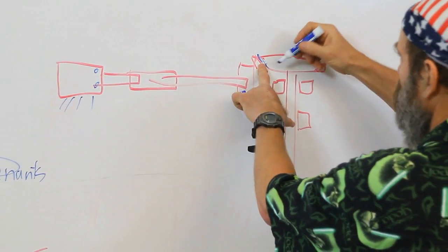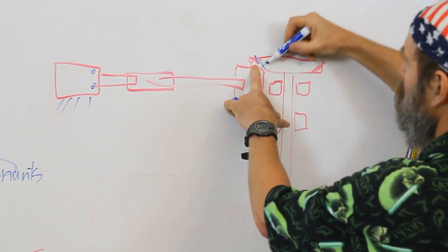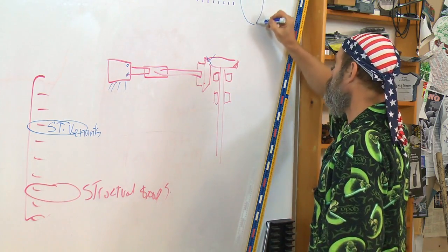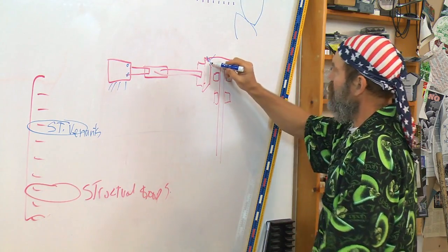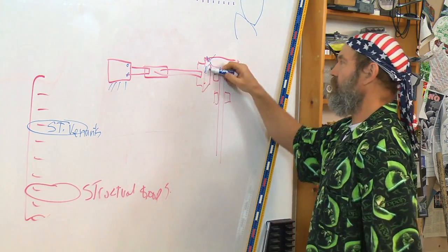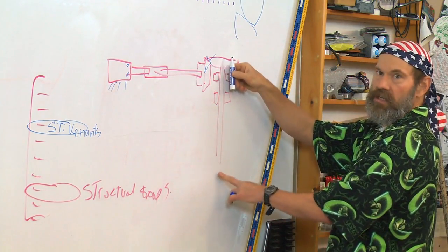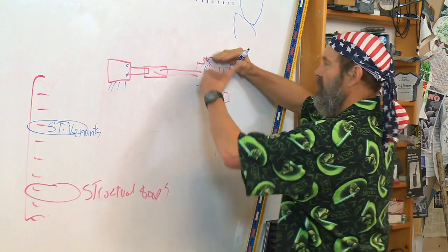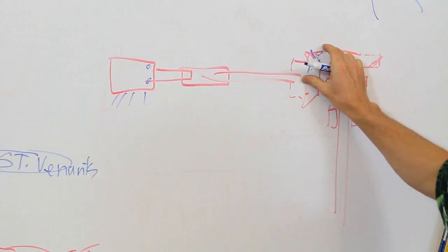In other words, when this gear pushes on this gear, it pushes back, and it wants to push away because of the shape of the gears, which is like a wedge. So it's going to push down, and as this gear here turns, if there's any torque put into this shaft, it's going to puck, puck, puck, puck. It's going to kick it away and skip teeth.